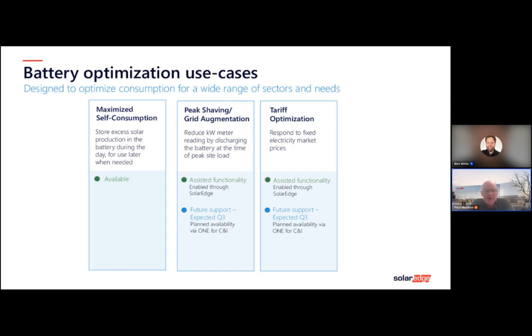So you can take a solar system that you have at the moment, and if you want to, add in the appropriate batteries. At the moment, we're doing it just on maximum self-consumption. So in effect, that is somewhat limited, but it shows the excess from the solar system going into battery storage, and then used as and when required based on the loads on that site.